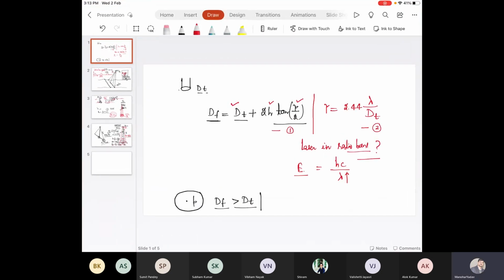The concept of atmospheric window does not apply here. It's an active remote sensing technique, and the imaging is done only at 1 kilometer height from the ground. I have already summarized that. Through different platforms we do laser scanning: ground based, vehicle based, and airborne or UAV based. In all these platforms, the target distance from the laser source is around 1 kilometer maximum in airborne.